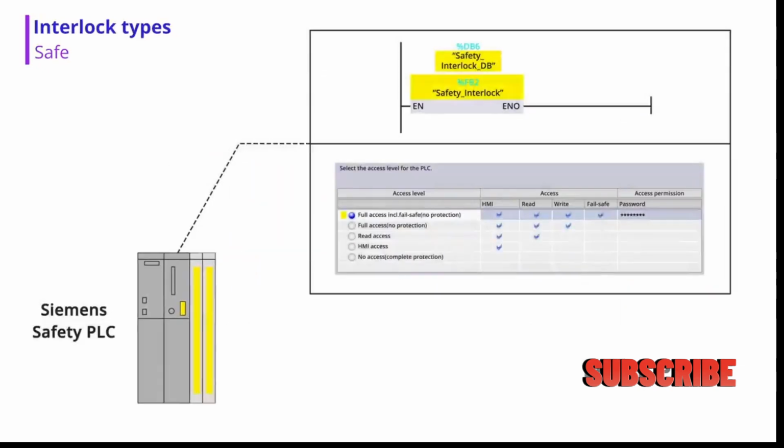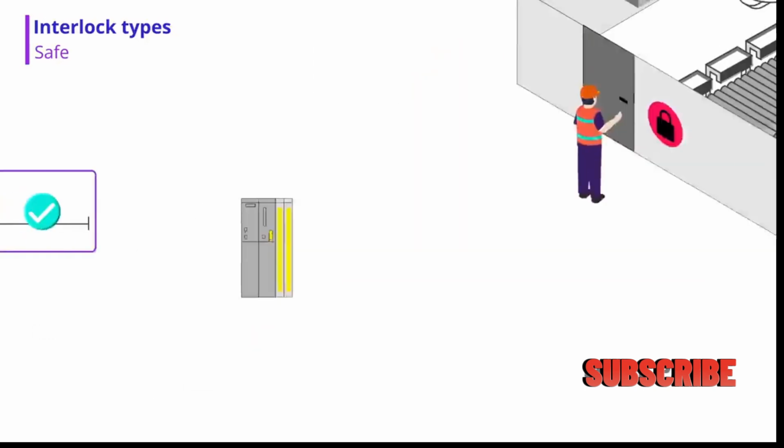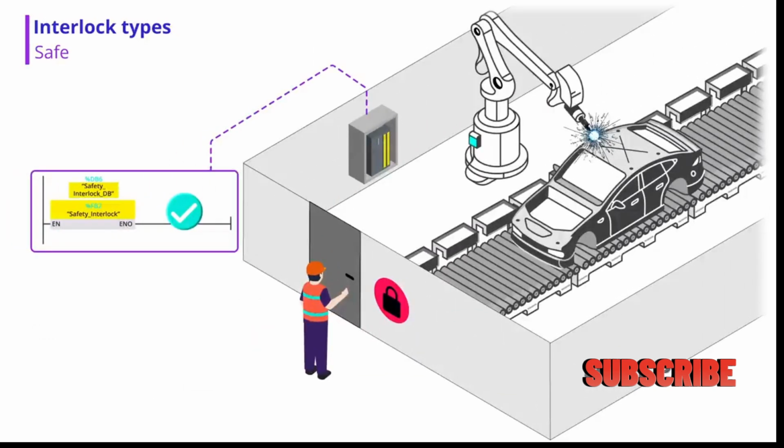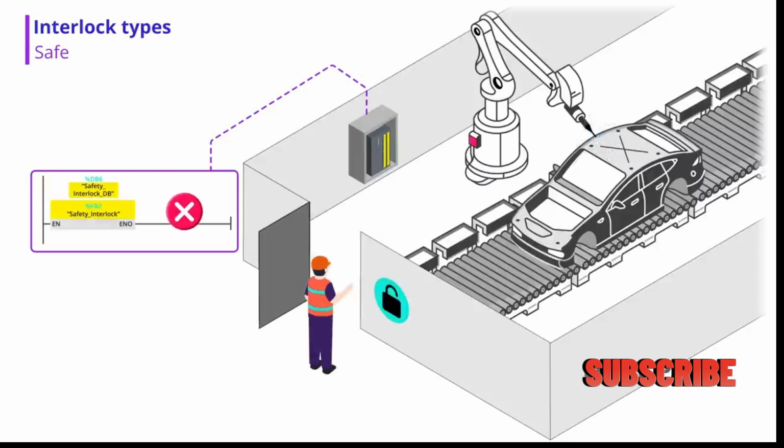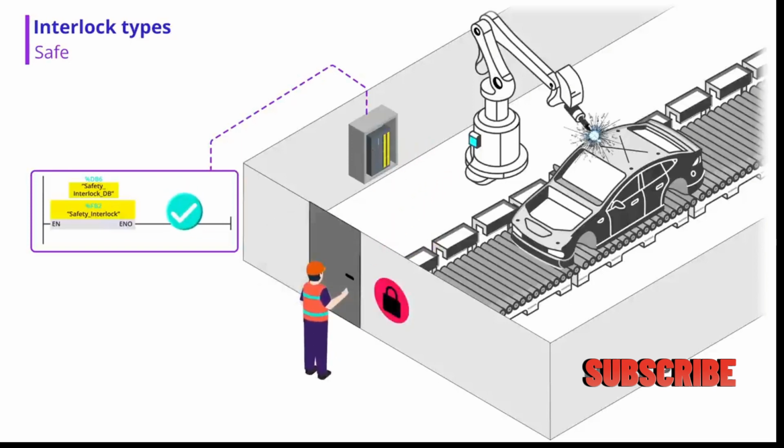The safety interlock shows how a programming instruction looks. These interlocks prevent people or things from receiving harm while the machine is running. For example, a safety fence on a robotic cell keeps people out of the cell to protect them from contact with moving objects. When the fence gate of the cell is opened, the safety circuit cannot be reset because the circuit is waiting for the gate to be closed. This prevents a person from walking into a robot cell while the robot is running.